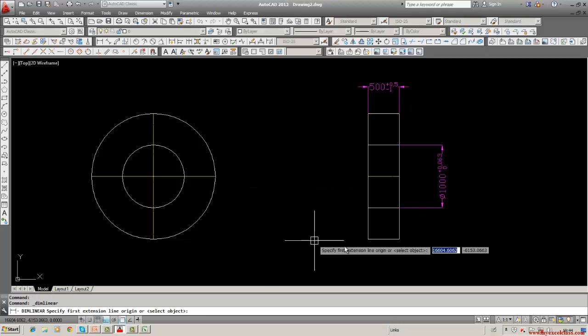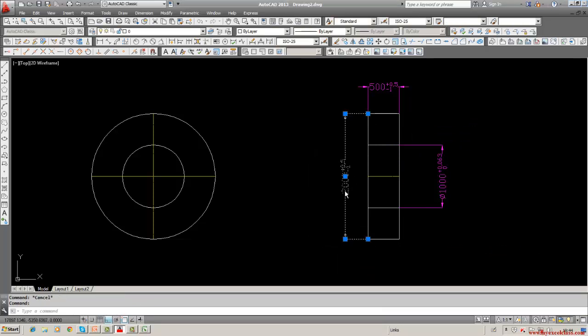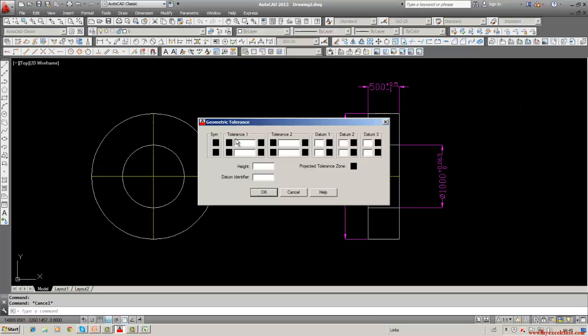I will take up the value here. See, 0.5. Let it be anything. It is not so wide a tolerance, it will be closer, but for our explanation purpose, I will take some tolerance. See, outside is also fixed. But there is one important factor. With this axis, this bore and the OD should be coaxial or concentric. Within what value? You cannot be 100% concentric, but it has to be concentric within a certain limit. So you can judge based on the purpose you need and with your knowledge.